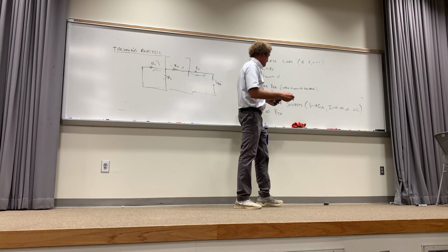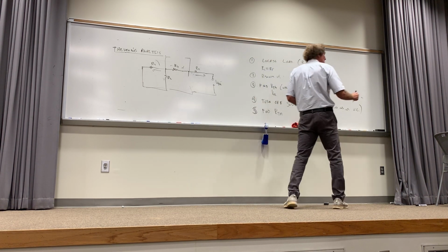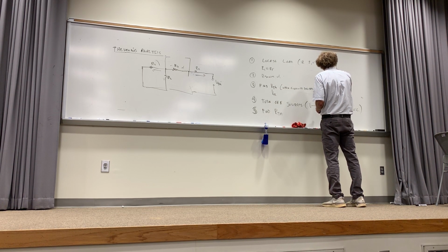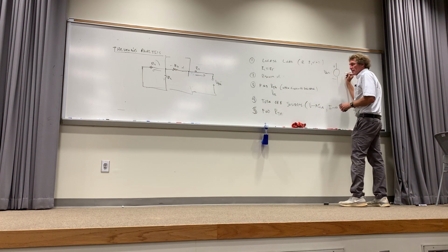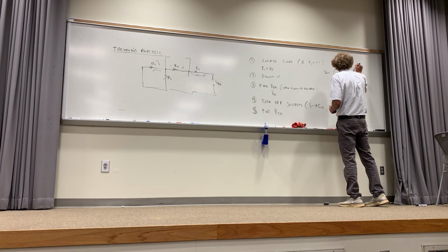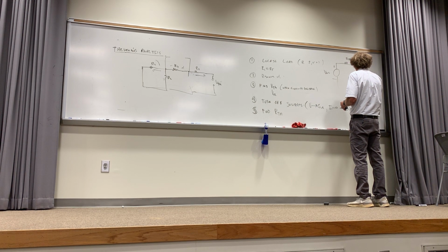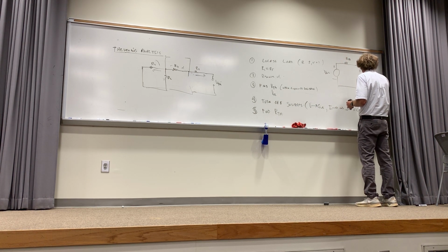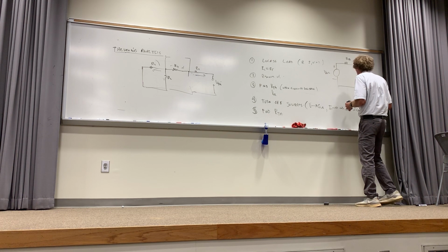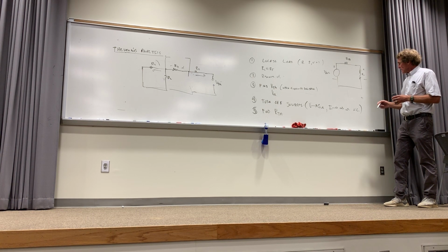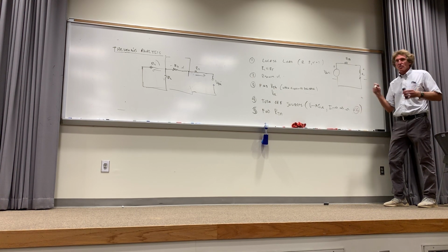Now, once you do that, once you find this RTH, you build this circuit. You put V open circuit here. Then you put R Thevenin here, the Thevenin resistance you just found. And then you reattach your load. Then you put plus to minus, now you put your load, RL, back in, and you find either the voltage or the current through that. Follow me? Yes, sir. What is that on the far right after I goes to infinity ohms? It's open circuit, OC, open circuit.